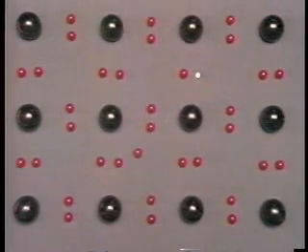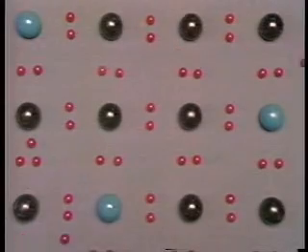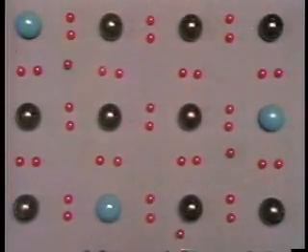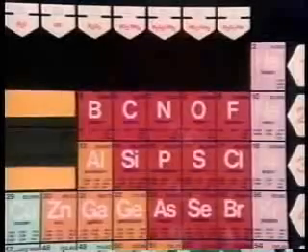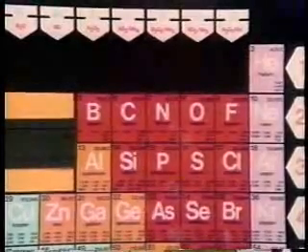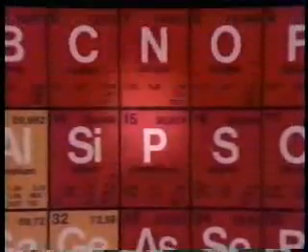This conductivity can be increased by adding impurities called dopants. Dopants are elements which are similar to silicon in atomic structure. There are 2 types of dopants. N-type dopants, like arsenic or phosphorus, have 1 more valence electron than silicon. P-type dopants, like boron, have 1 less.